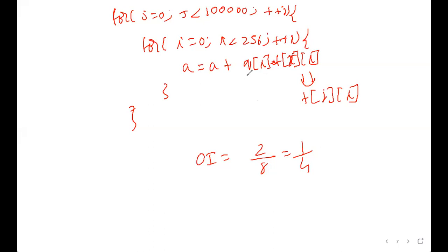If you assume Q is present in some register array, because you get the query and store it in some register array inside the FPGA, you only stream this. So the initial cost of bringing Q is negligible, so we can keep that aside. Here 2 represents the multiplication and addition, but 4 is because you are not getting Q every time; the only data you're getting is f of ji, which is 4 bytes long. Okay.